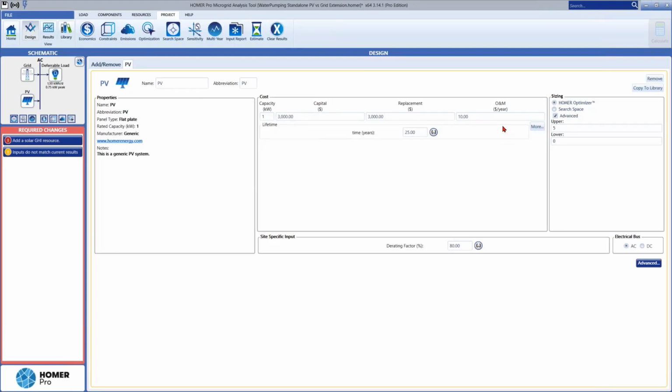Boy, I can go into a lot of detail here. O&M for generators is based on operating hours, and O&M for PV and inverters is based upon calendar time. And that's important.